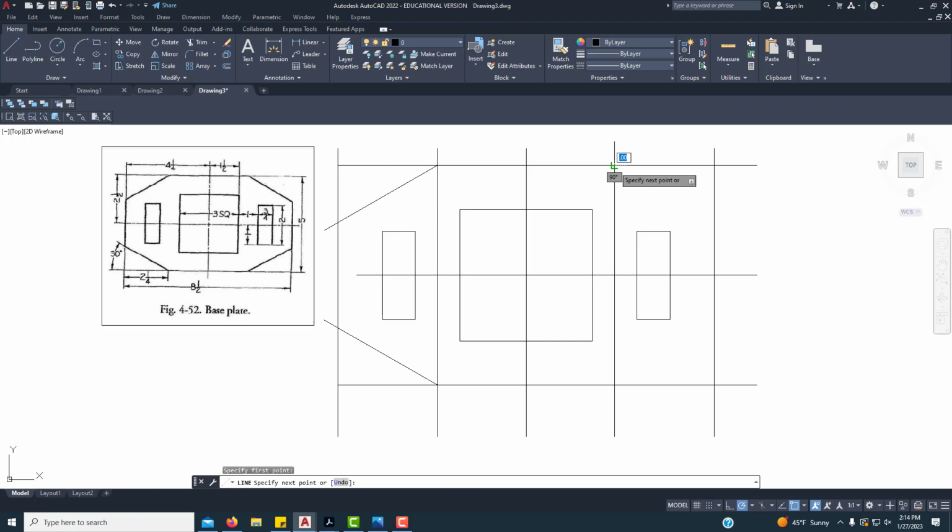If we come from this intersection going straight out, that's 0, or if we're in a full circle, it's 360. But if we need it, 360 minus 30, that could be either input as negative 30 or 330 degrees. And then we'll do the same thing here on the bottom. I'm just using the line command, clicking on that intersection, making sure my coordinates are what they need to be here. So here is 0. We're actually going up 30 from 0.